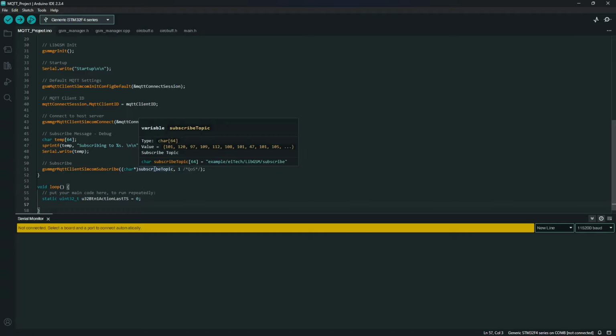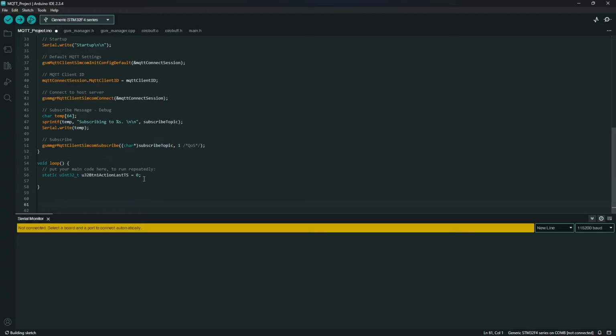And then I'm going to make 2 different states with this button. So the first state I'm going to make static int, and I'm going to call it int button 1 state, and I'm going to make that equal to 1. So this is assuming a default of 1 is not pressed. Okay, and then after that, I'm just going to copy this to save some time again. And the next variable that we're going to have is going to be our button 1 state last.